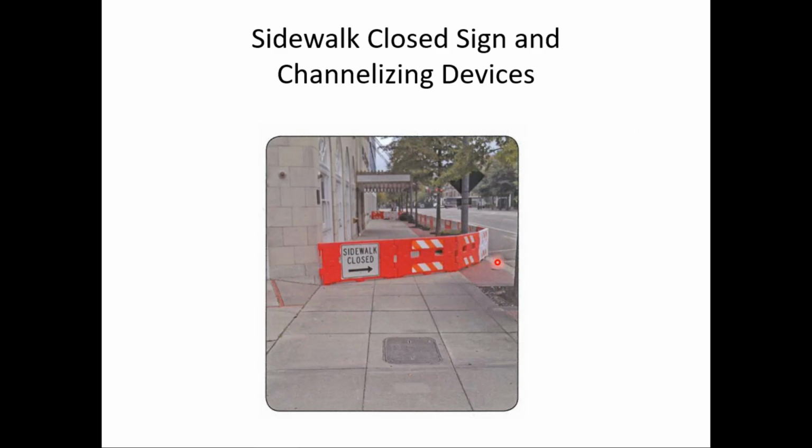But notice that there's no curb ramp to get them from the sidewalk to the street, nor is there any, there should be channelizers here to separate pedestrians from the vehicular traffic. So I'll give them partial credit for the way they closed the sidewalk, but not any credit for the way they handled pedestrians in terms of an alternate path.